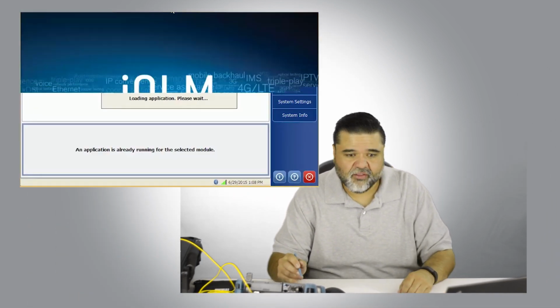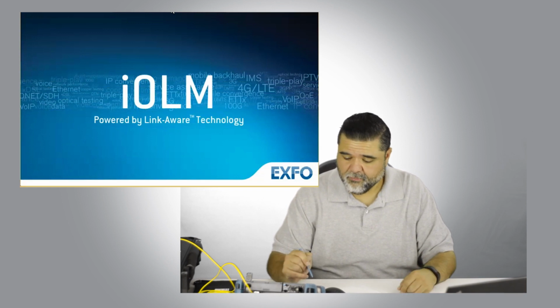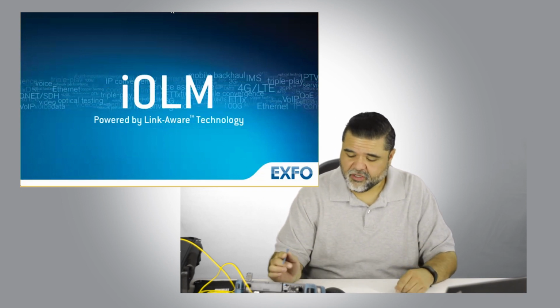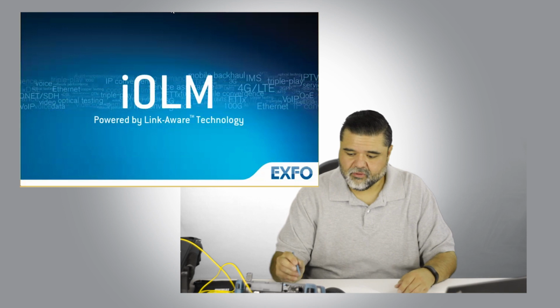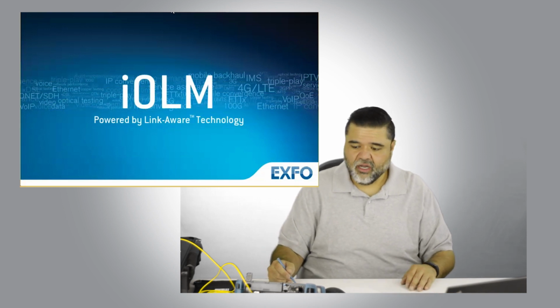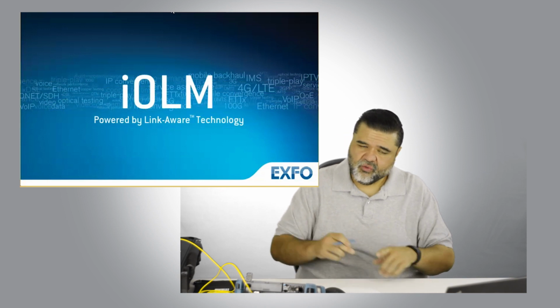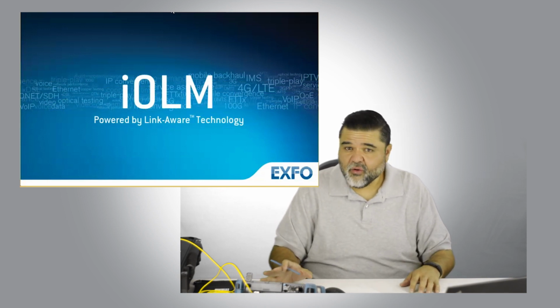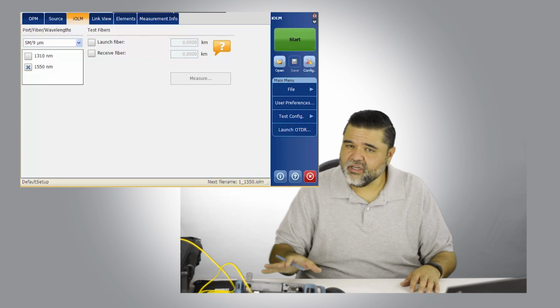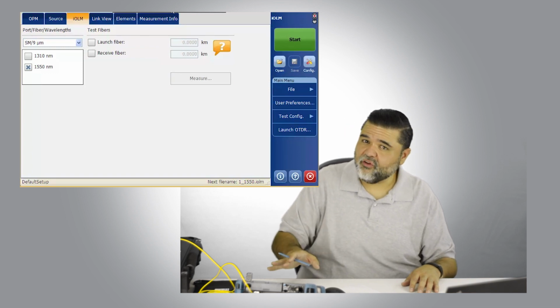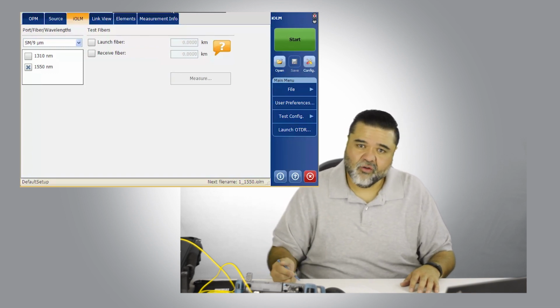You see here on the display that we have OTDR or iOLM, so you can run both. In this particular training, of course, we're doing iOLM, so I'm going to launch the iOLM module here and let that fire up. One of the first things we'll do is get in there and configure it. And the great thing is, once it's configured, you really don't have to do anything but clean fibers and hit start, and then you're off and running.